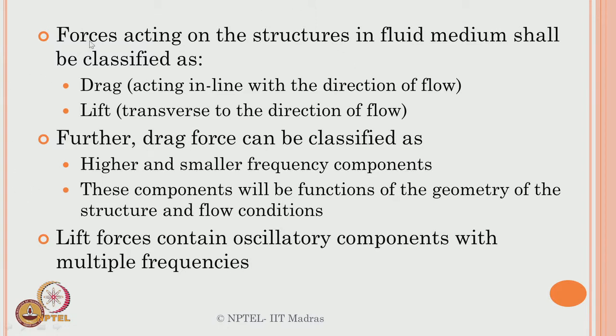Therefore, forces acting on the structure in the fluid medium can be classified into two: the drag and the lift forces. Drag is what we call the inline force acting in the direction of flow. Lift is transverse to the direction of flow. There are two ways in which the flow characterizes the forces on the member. Further, the drag force can be classified into higher and smaller frequency components, which we call springing and ringing responses, explained later in the part on TLP dynamic analysis.